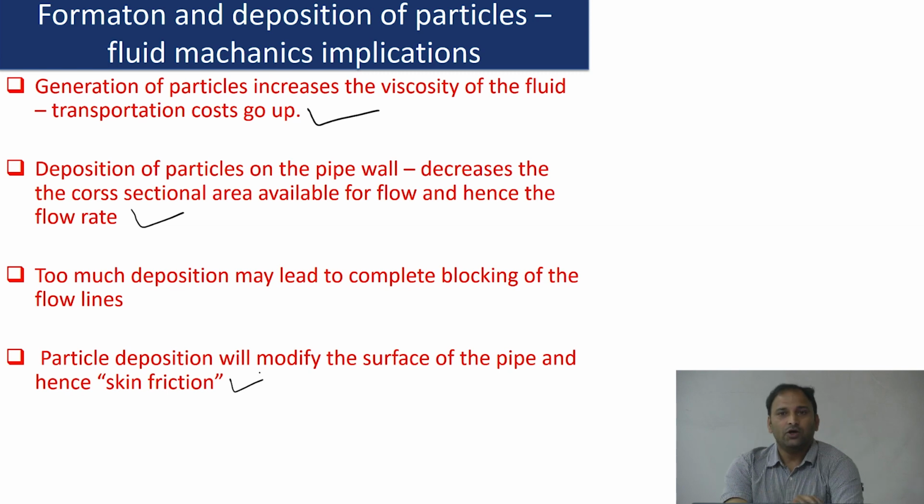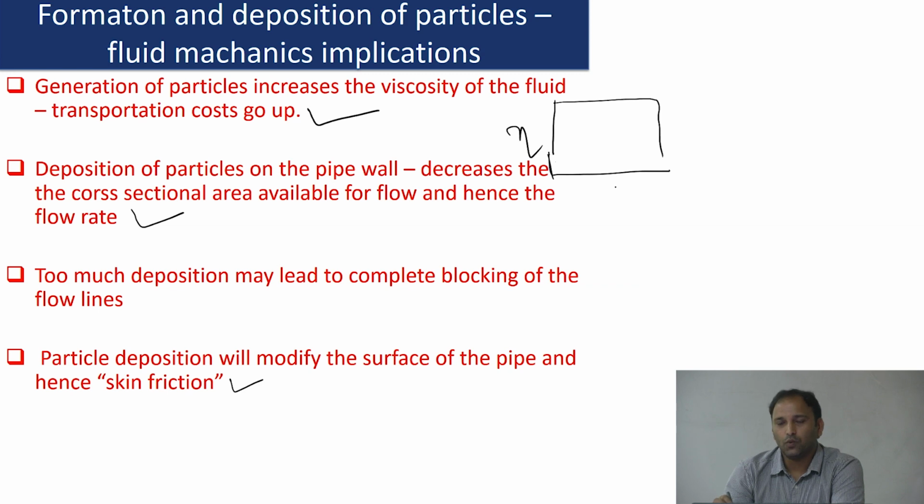The first point. Were you there for one of the classes where I talked about viscosity measurements? Okay, so let me just draw something here. We had discussed a particular plot where the viscosity was measured as a function of, say, shear stress. Okay, wherein we said that the viscosity would remain constant as a function of shear stress when you have a case where you only have a fluid. Now I put in a small amount of particles. What happens? The viscosity goes up.